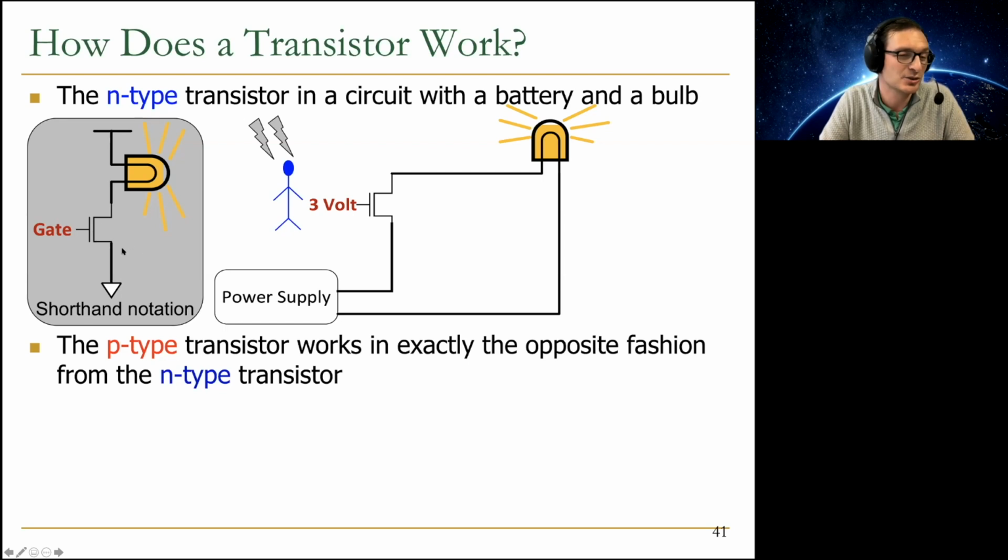If the voltages are too low, you cannot really turn on the gates. They need to be above some threshold, basically. In fact, it's called a threshold voltage. To enable a transistor, you need to be over a threshold voltage. And there are different operating regimes of a transistor, which I'm not going to go into right now. So it's not as simple as I described. There are some linear and nonlinear operating regimes, but we're not going to talk about that right now. Well, certainly we're not going to talk about that in this course.